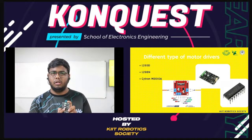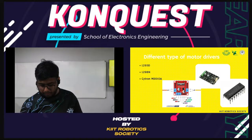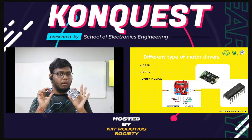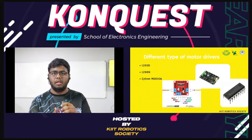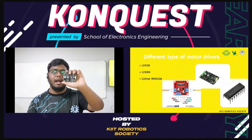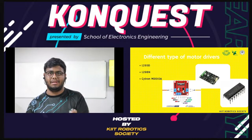Same goes with this one, you can also connect two motors with this motor driver. You can run this, no issues. What's the difference? Current consumption. With this, the max output current is 1.2 amps, and with this, the max output current is approximately 10 amps.